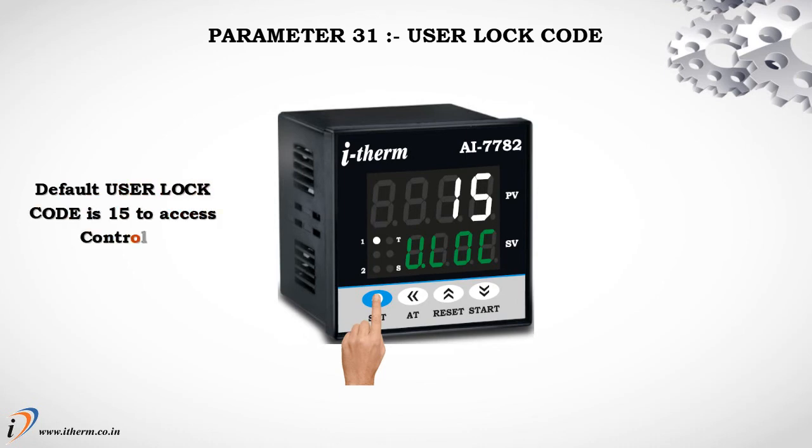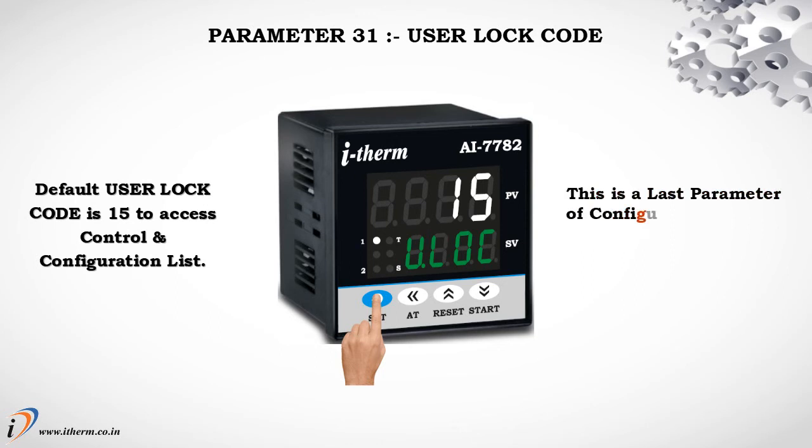Parameter 31, user lock code. The default user lock code is 15 to access the control and configuration list. This is the last parameter of configurational mode. Press the set key to enter in run mode.